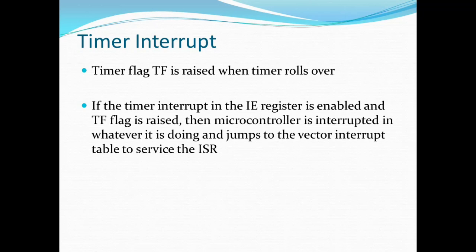But even though your timer flag is set to 1, you have to set some particular value in the interrupt enable register, which is called the IE register. Through this register you first have to enable the corresponding timer interrupt, and only then will your microcontroller get interrupted, stop whatever it is doing and transfer the control to the interrupt service routine.